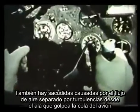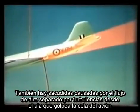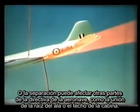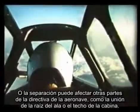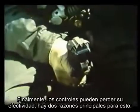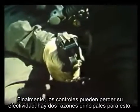There is also buffeting, caused by the turbulent separated airflow from the wing striking the tailplane. Or separation may affect other parts of the aircraft directly, such as the wing root junction or the cockpit canopy. Finally, the controls may lose their effectiveness. There are two main reasons for this.